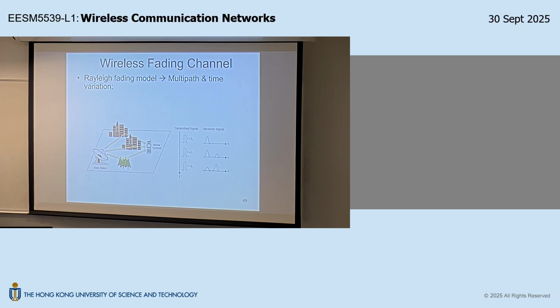Remember in day 1 when we talked about the introduction, I had this toy example with a coaxial cable, talking about long distance communication. At that time we said that the coaxial cable will have 2 effects on the signal being transmitted. One is noise, right? Second is attenuation. The signal will get weaker and weaker as it propagates down the coaxial cable. So what's the physics behind the attenuation? Ohmic loss, right? Because the coaxial cable has resistance, as the signal travels through these resistive elements, you have I squared R loss. That's the reason you have attenuation in a coaxial cable.